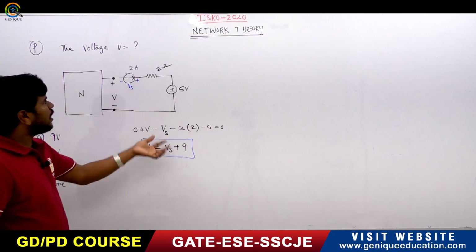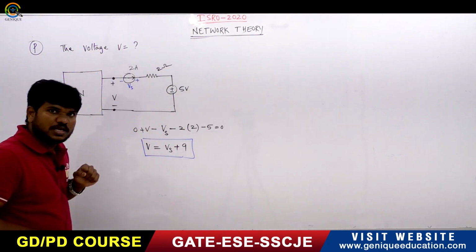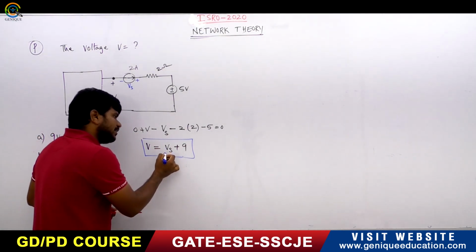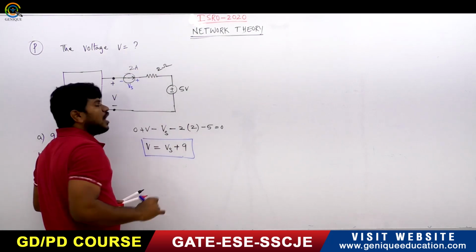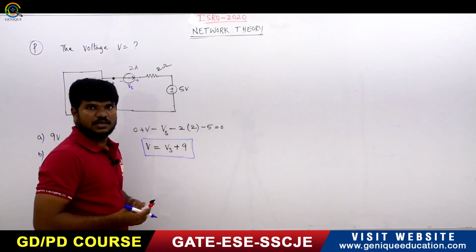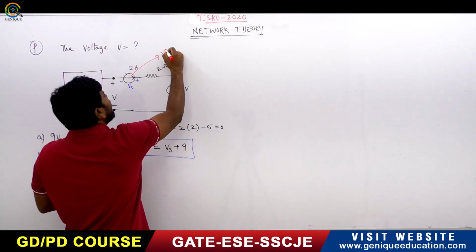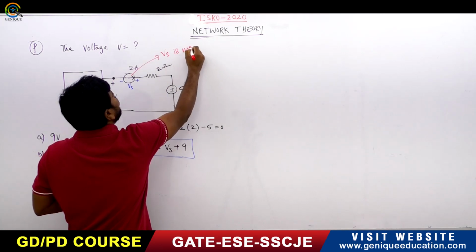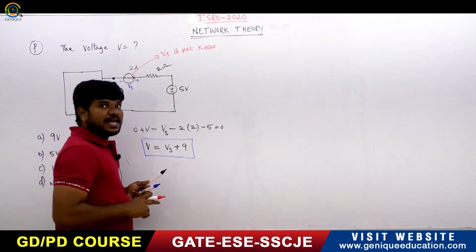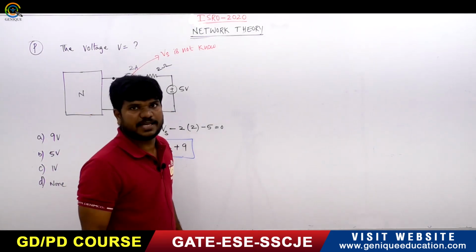But you don't know the voltage of this current source. Mostly what people will say is to write the voltage across the current source as 0. But that is a wrong practice. Okay. So Vs is not known. What is the Vs? The voltage across the current source is not known until it is specified.